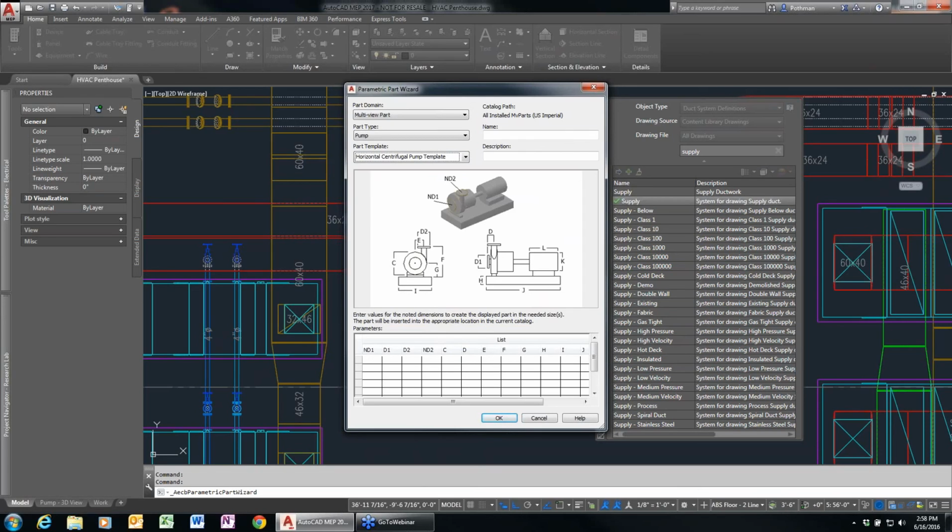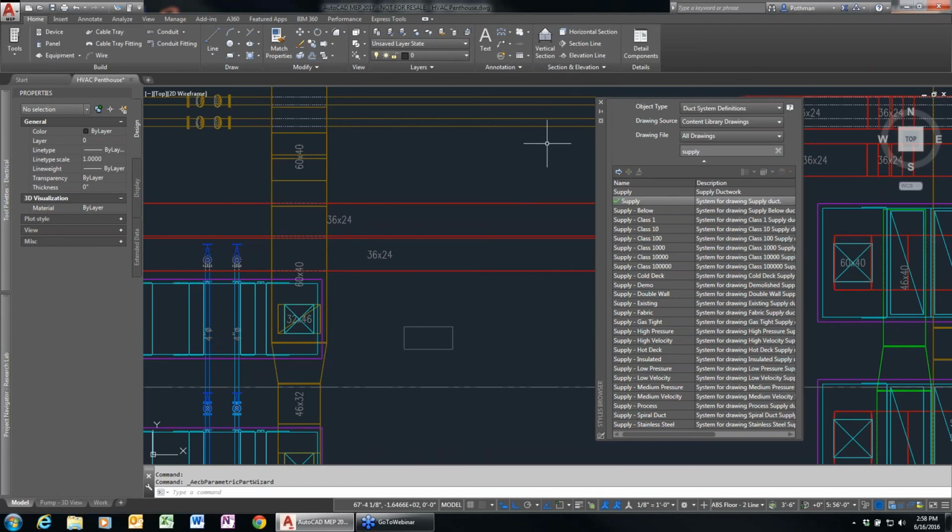I guess one last question here, since we're coming up on the top of the hour. Want to know if things can be transferred to Revit using IFC, and yes, there's an IFC export and import, so you can. It basically will bring the geometry across, but not all the intelligence. So you'll lose the intelligence from that, but you can bring the model across.